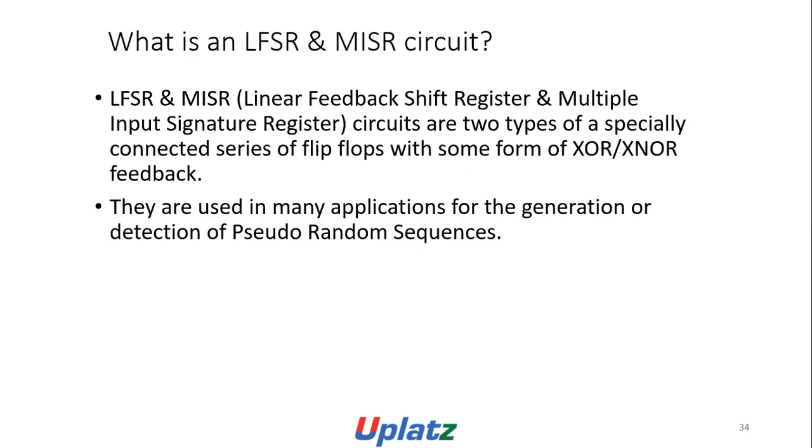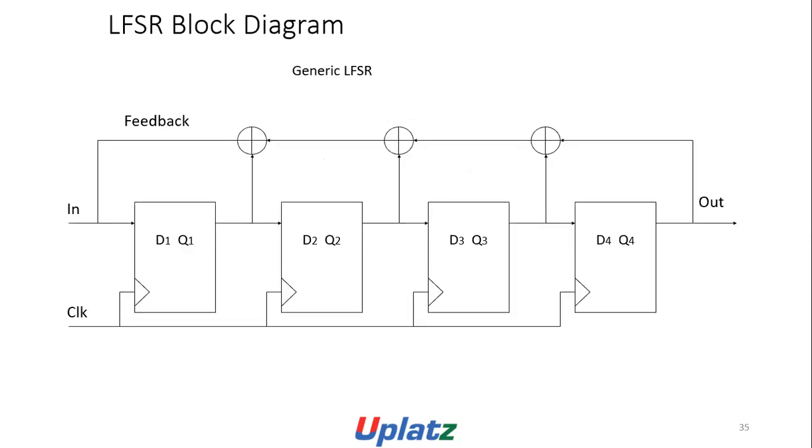What is an LFSR and MISR circuit? LFSR and MISR, linear feedback shift register and multiple input signature register circuits, are two types of specifically connected series of flip-flops with some form of XOR or XNOR feedback. They are used in many applications for generation or detection of pseudo random sequences.